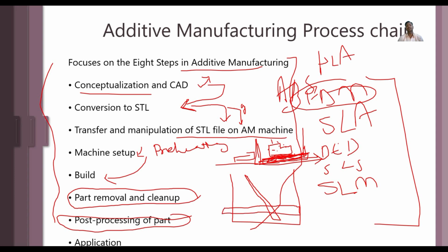So due to such cases, we put the inclination, but we put some support so that it will be able to print in that particular area. At a later stage, this can be removed by post processing. This kind of arrangement and analysis can be done in the build stage.